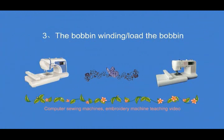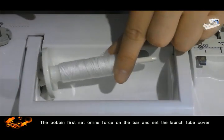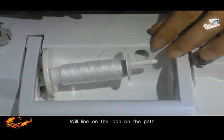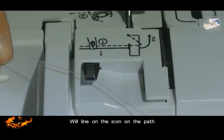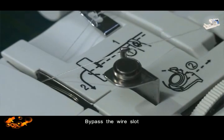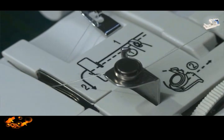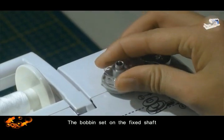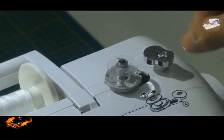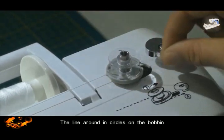3. The bobbin winding/load the bobbin. First set the thread on the rod and set the thread cylinder cover. Follow the icon path with the thread, through the wire hook, and then through the wire cover. Bypass the wire slot. Set the bobbin on the fixed shaft. Wind the thread around in circles on the bobbin.